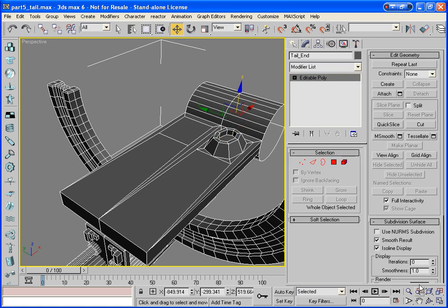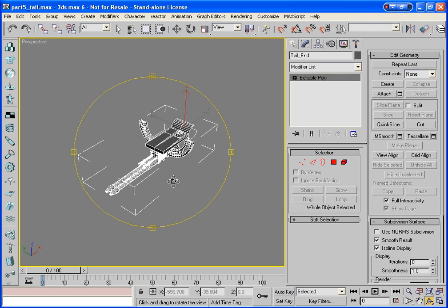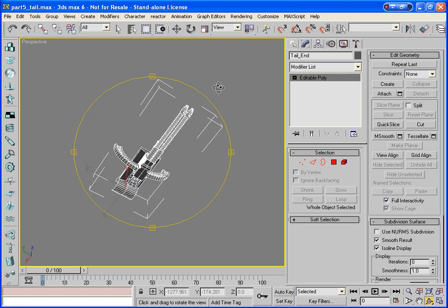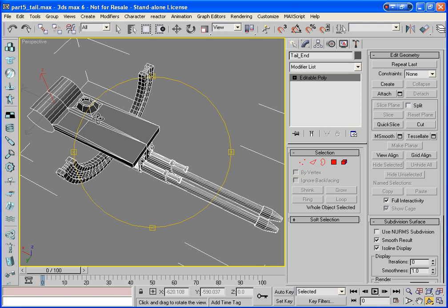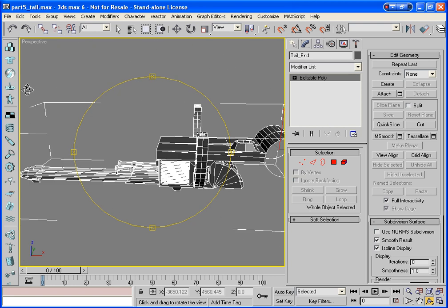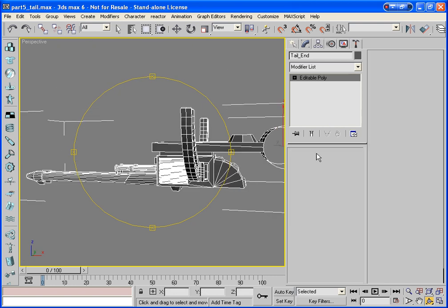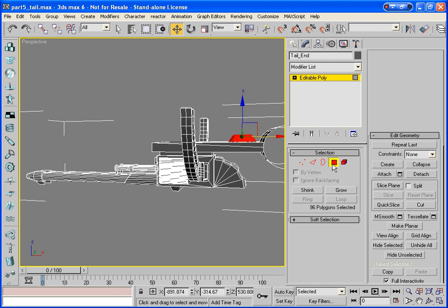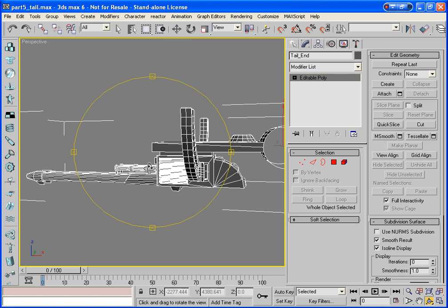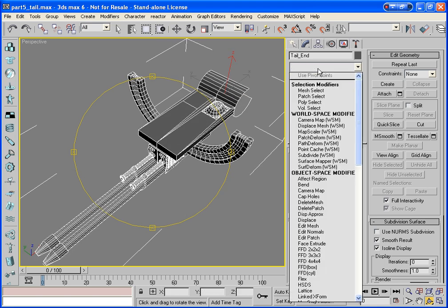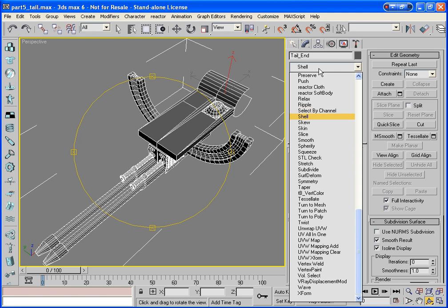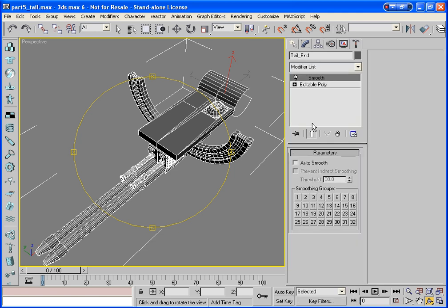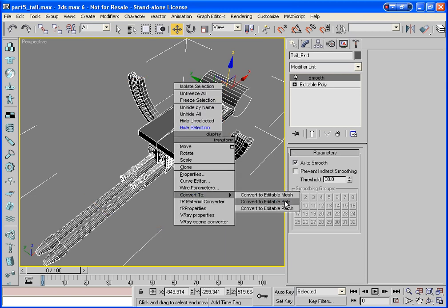There we go, one area for the plug to go. And I think what I'm going to do is, because I'm a horrible cheat, just select these bits and click Mesh Smooth. There we are. Finally, I'm going to attach a smooth modifier to it. And click Auto Smooth. And it'll just get rid of some of the jaggies and then just convert it back.